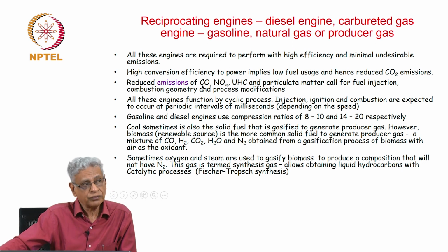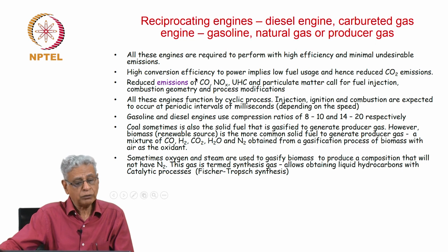Reduced emissions of carbon monoxide, oxides of nitrogen, unburnt hydrocarbons and particulate matter call for fuel injection, combustion geometry and process modifications, which are actually not the same as obtaining high conversion efficiency.